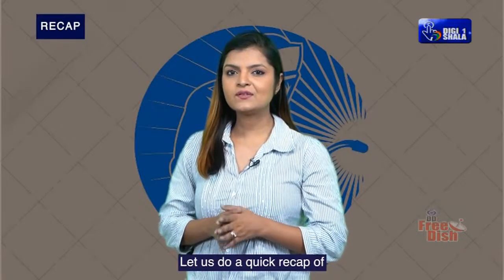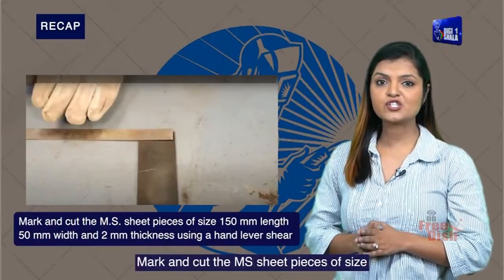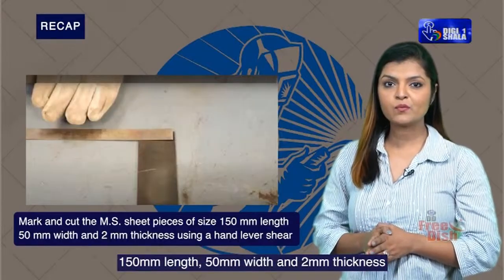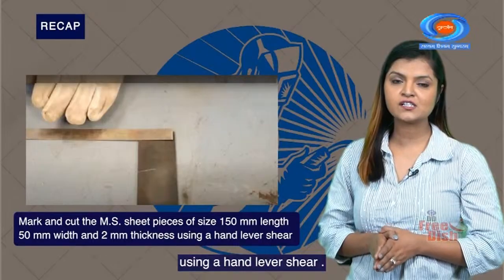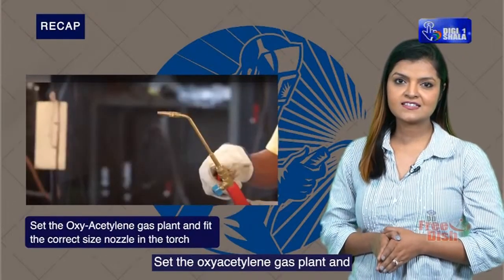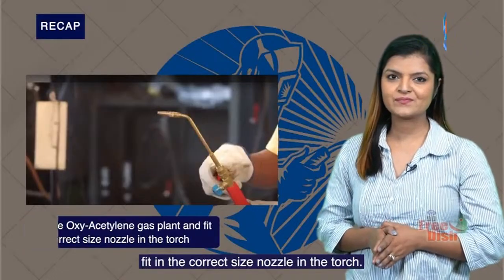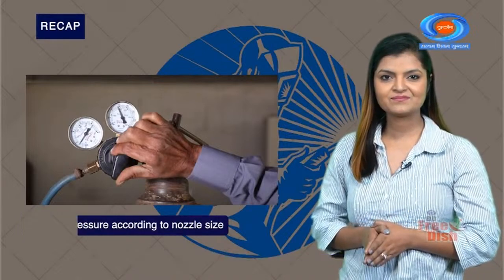Let us do a quick recap of what you have learned from this topic. Mark and cut the MS sheet pieces of size 150 mm length, 50 mm width and 2 mm thickness using a hand lever shear. Set the oxyacetylene gas plant and fit in the correct size nozzle in the torch. Set gas pressure according to nozzle size.